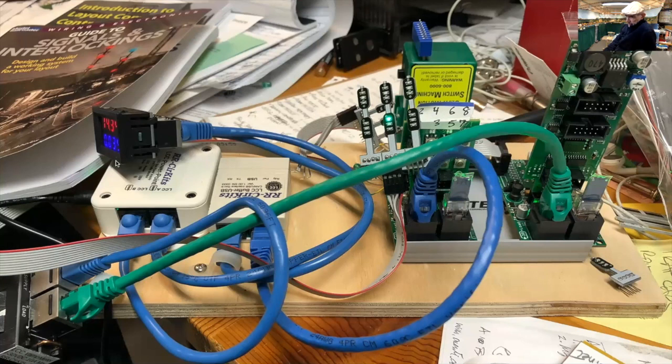I also found that they sell a volt amp meter so that you can actually monitor the performance of the CAN bus. And in this case, it's showing that I have something like 0.03 amps and 14 volts, which is fine. I also didn't mention, but all of these components connect together through standard Cat5 Ethernet cables. So it's very easy to do the wiring without a bunch of extra work.